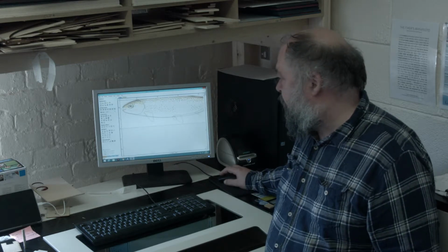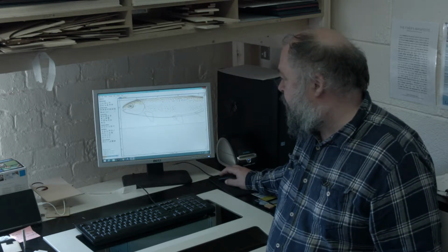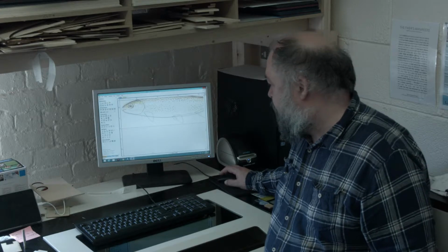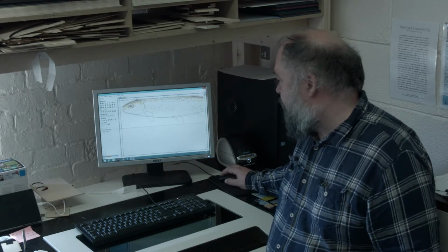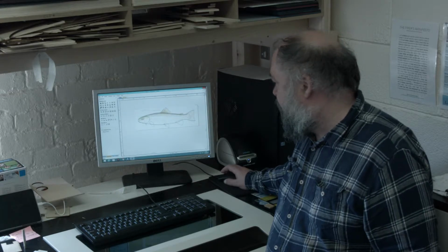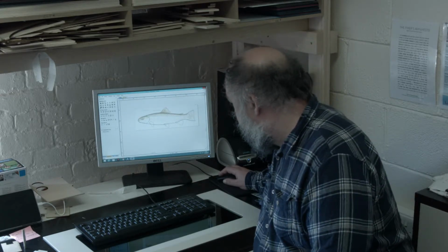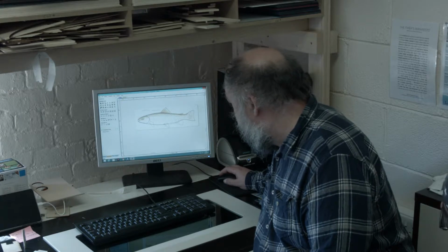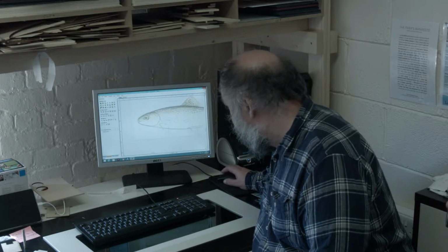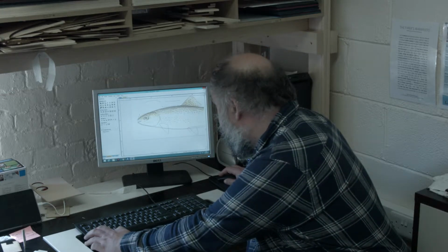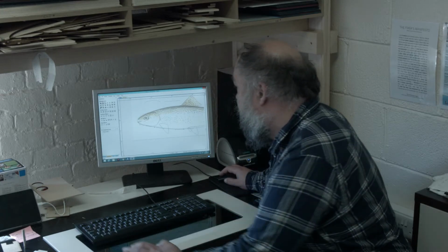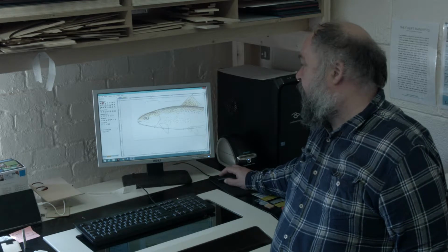So what I want to do initially is this 2-rail sweep, which is under modelling. So select the two vectors I want, and then go to 2-rail sweep.